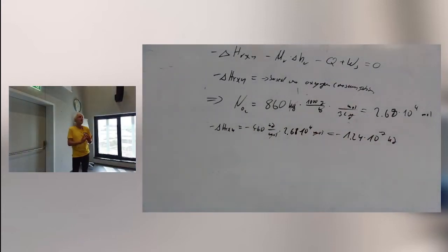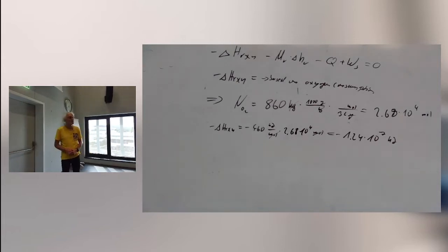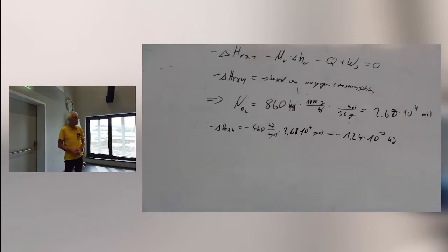A power is not an energy, just physics first class. Don't forget that. Energy is power times time. So you have to multiply that. If it's 15 kilowatts, you need to multiply that by 48 hours, and then it's an energy, and this you need to convert into kilojoule in order that you can subtract it.